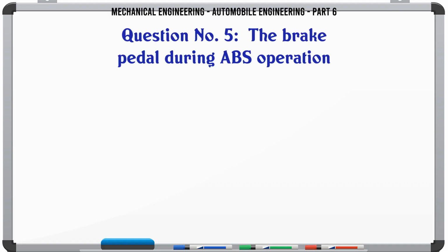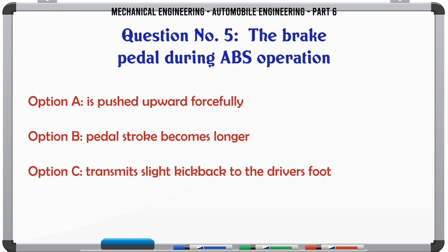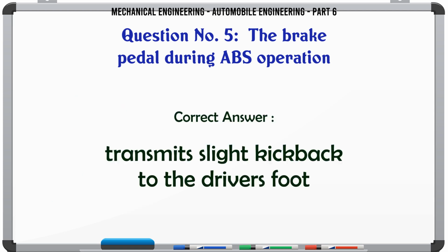The brake pedal during ABS operation: A. is pushed upward forcefully, B. pedal stroke becomes longer, C. transmits slight kickback to the driver's foot, D. all of the above. The correct answer is transmits slight kickback to the driver's foot.